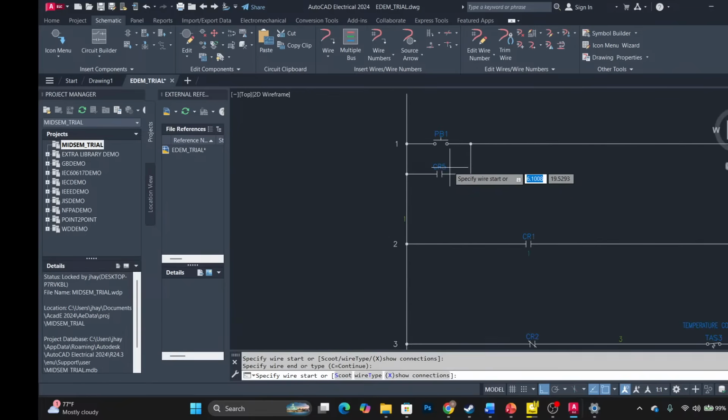And then you know what will happen. This is now serving as a sealed-in hot circuit. So whenever you press the push button, this closes, so when you release it, there's still current flow. That's what is going on. Good. Now let's look at the PDF.